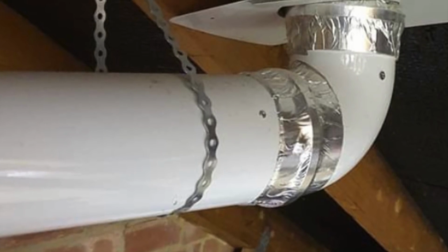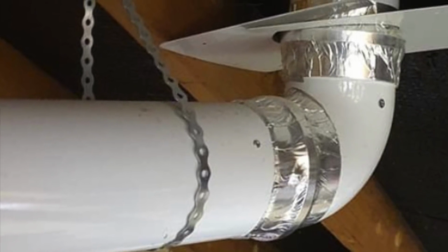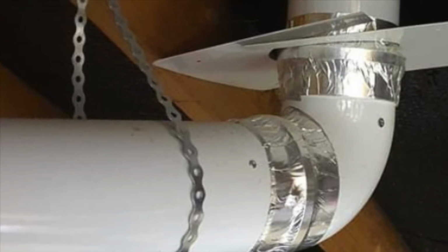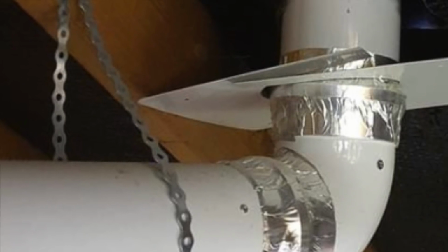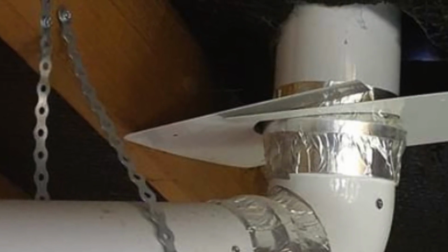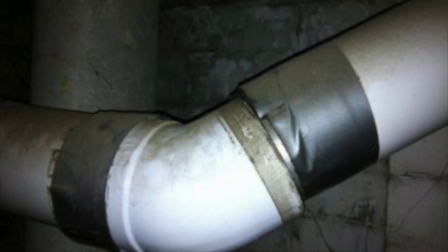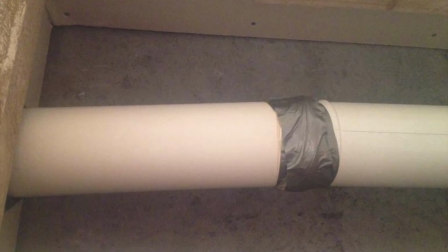Now, you may come across some flues which are secured with this band strapping, which used to be quite common, but now is not allowed because this flue is still unsecured. So again, it would be at risk. And also they've used this silver tape to secure the joints, which again is not allowed. So you're not allowed to tape up your joints whether you're using closure plate tape or duct tape. It's just a no-no. It does not make the flue secure. So use the correct clips to the manufacturer's instructions.